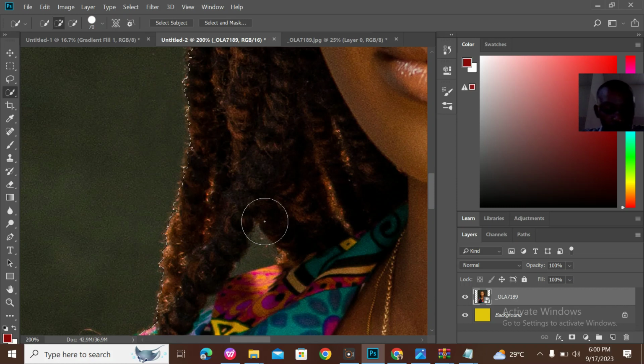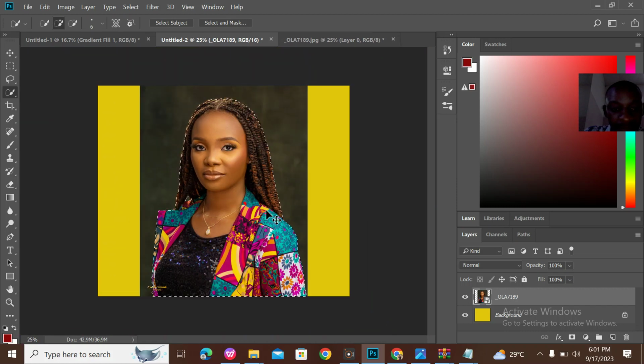Okay, so if you want to select inside, once your hand hits the alternate key, the plus in the middle of this selection tool will become minus. Okay, I see it has become minus. Observe guys, it has become plus, it has become minus. So I'll reduce the size by using the lower bracket tool, okay, because I'm selecting a smaller area. So my hand will be on alternate, okay, that's my mid finger. My thumb will be on the left click, and then I'll select. Okay, so I have selected this area.